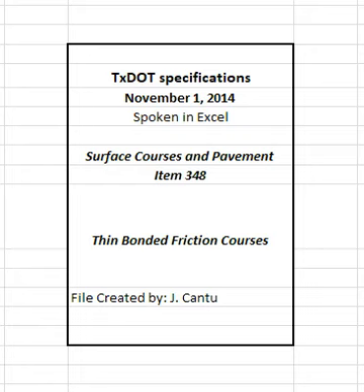The engineer may perform tests at any time during production, when the contractor blends Class A and B aggregates to meet a Class A requirement, to ensure that at least 50% by weight, or volume if required, of the material retained on the number 4 sieve comes from the Class A aggregate source. The engineer will use the department's mix design template, when electing to verify conformance, to calculate the percent of Class A aggregate retained on the number 4 sieve by inputting the bin percentages shown from readouts in the control room at the time of production and stockpile gradations measured at the time of production.